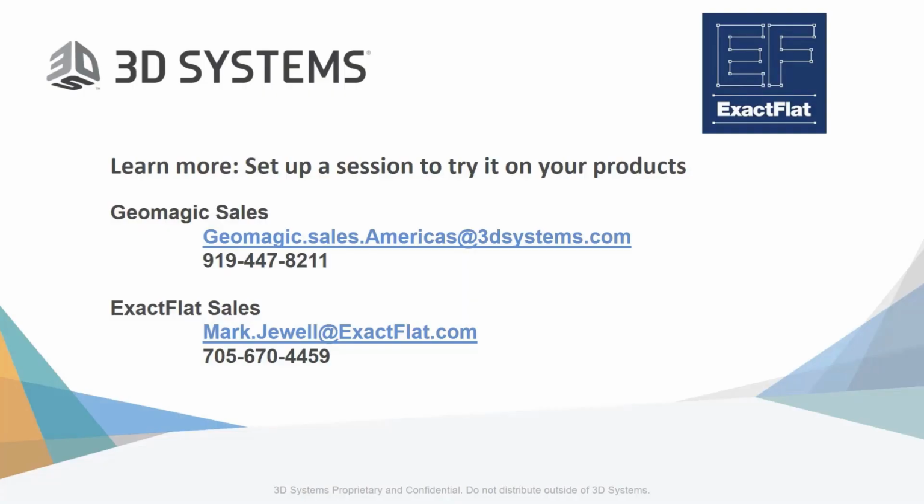Mark, it's all yours. The first question is, how do you create cut lines or seams on a part? For this, you have a number of options, but the recommended way is to create the seam definitions by drawing lines on your part in the Design X portion of the workflow. They can be done in SOLIDWORKS later on, but it is best to do it earlier in the workflow.